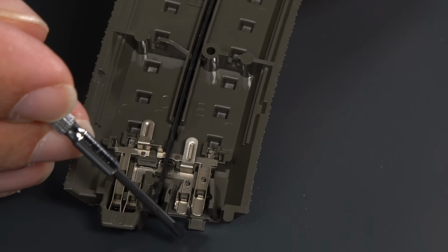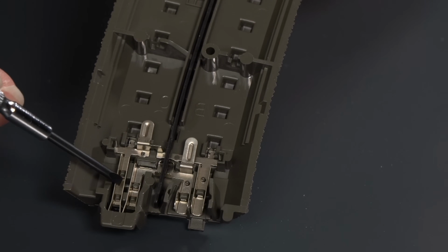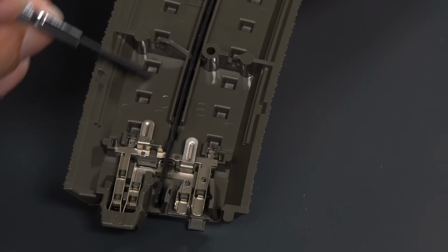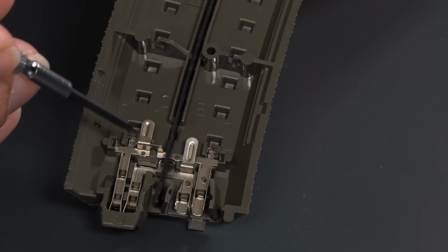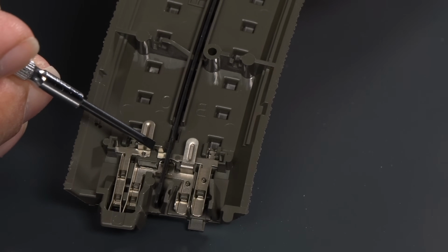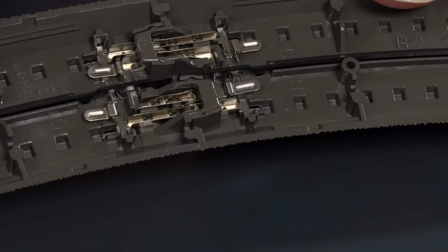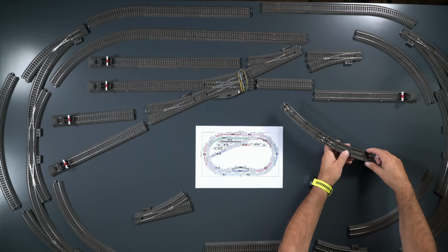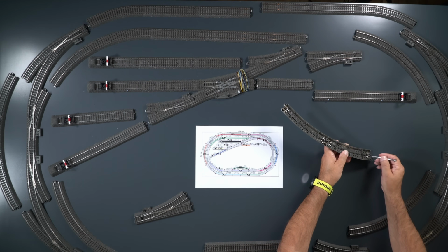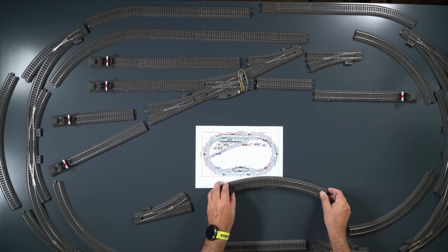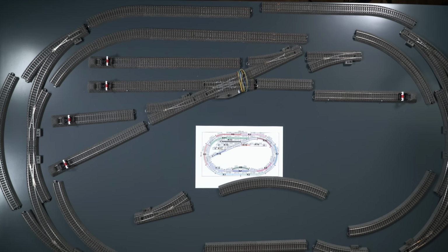So I can either insert the neutral conductor into the track from here, but in this case I don't want to do that. I want to strip one side here accordingly, and for that I need to cut this bridge. You can see it here very clearly with a small pair of side cutters. The same applies here. At this spot the bridge needs to be cut, and of course also at this spot at the end of the track exactly the same thing. Here too I have another connection, which means for my two tracks there are basically 4 spots that I need to cut.